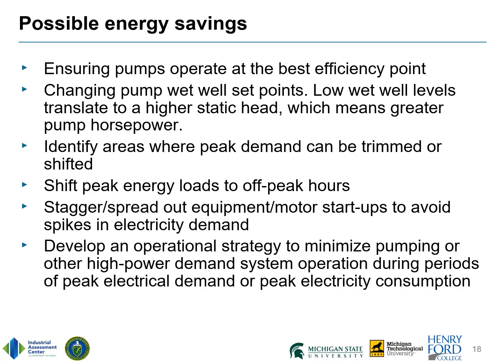Possible energy-saving tips for wastewater treatment plants include ensuring pumps operate at the best efficiency point, changing pump wet well set points, identifying areas where peak demand can be trimmed or shifted, shifting peak energy loads to off-peak hours, staggering or spreading out equipment and motor startups, and developing operational strategies to minimize pumping or other high-power demand system operation during periods of peak electrical demand or peak electricity consumption.